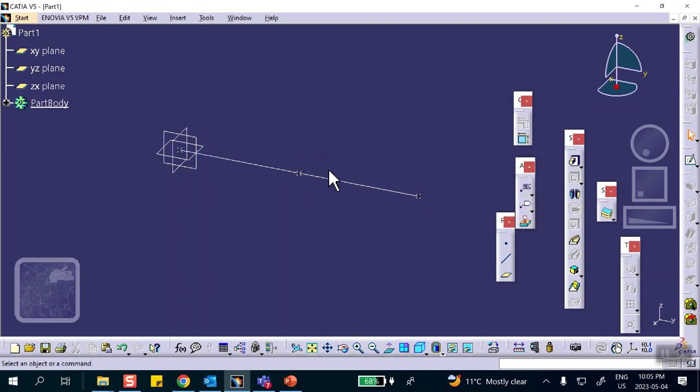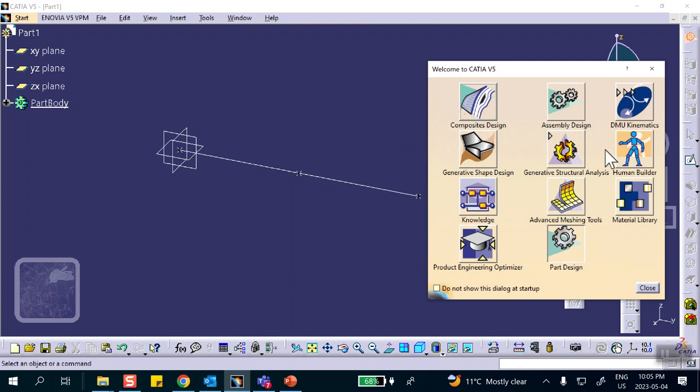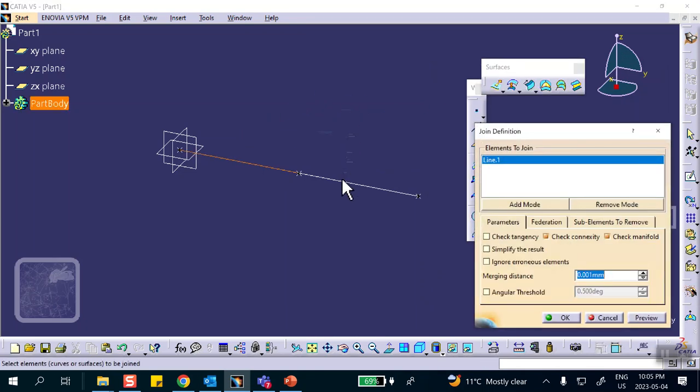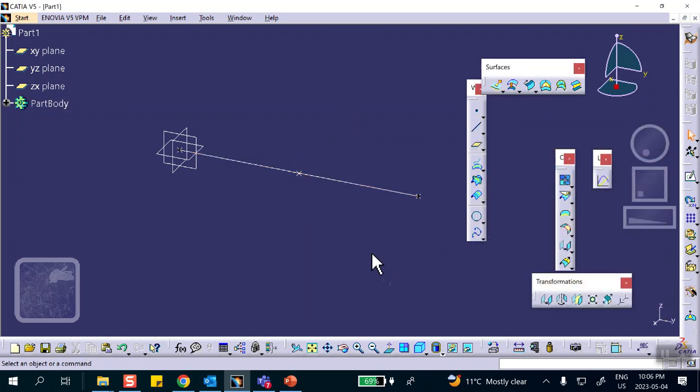And because I have to mesh these with beam elements, there is no way out of that. Here you have to create these with beam elements, because once you create the beam element, then you can create your spring elements later. Okay. So first of all, I don't want duplicate nodes in the middle. So why don't I go ahead and join these two lines. That means that when a mesh is created, the point in the middle is not going to be a duplicate node. That's the only reason behind this joining.